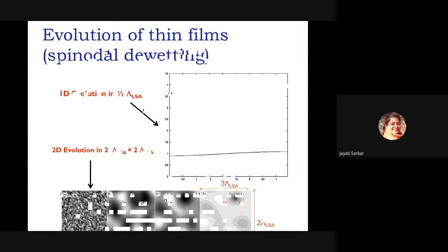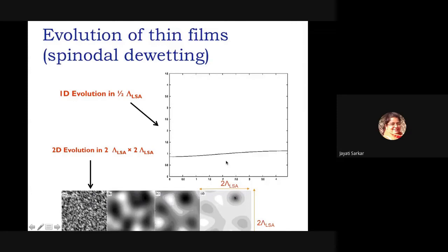So we will show you how, in the case of a half lambda, this film is evolving. This is the surface which has been perturbed, and this wave is getting modified. Here you see that the initial thickness has reached the surface at near zero, and the liquid film is forming a rim, right? And this rim is getting filled up by liquid, and this is ultimately forming a half droplet in a length scale of half lambda.